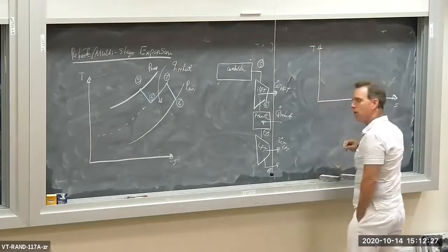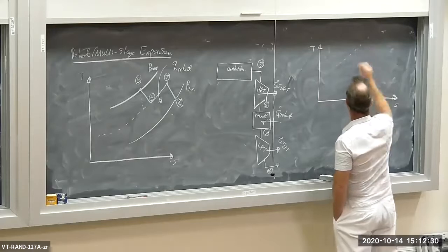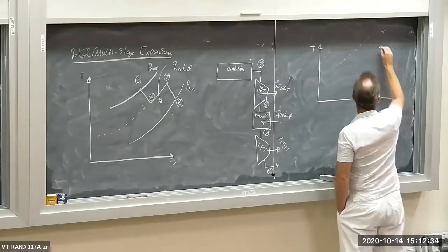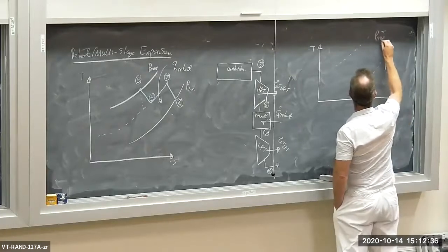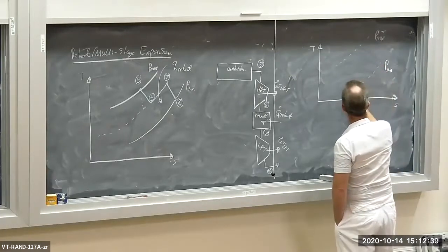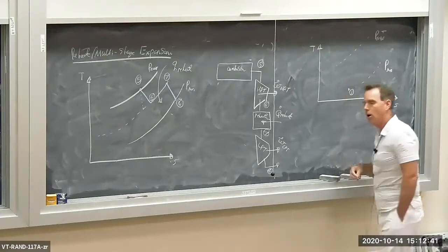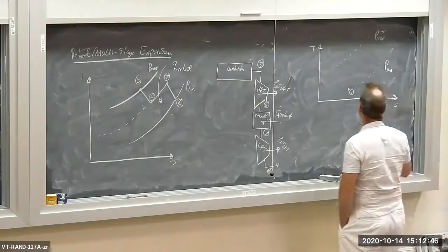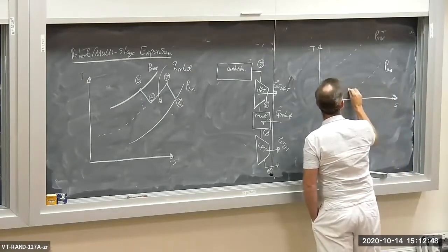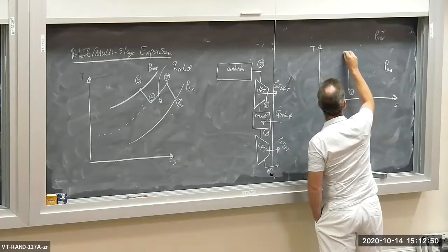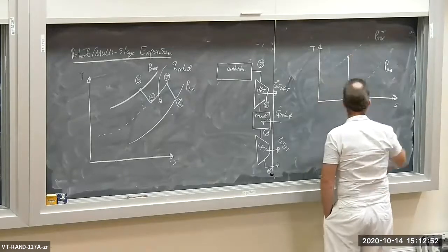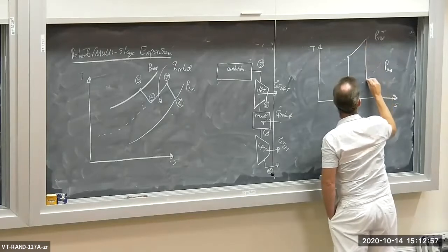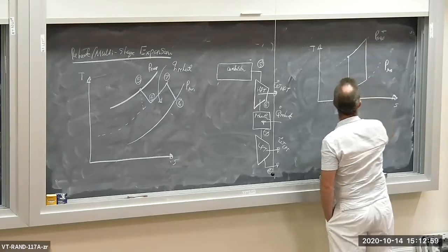Now let me take the original, so let's have the original P max and P min isobars in the cycle. Now originally, for our regular Brayton cycle, let's say it's reversible, let's say it's an ideal Brayton cycle. Originally, we have compression all the way up to state 2, then we have heat addition, and then we have expansion in the turbine and heat rejection.